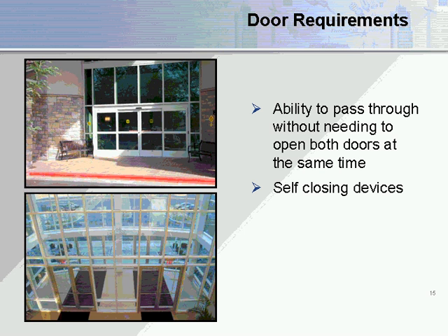Okay, also from a door requirement, we talked about the ability to have self-closing doors. So, what you can use, power-operated doors, the upper right-hand corner, this is a power-operated door. This would be fine. These are used quite extensively in a lot of buildings. A standard self-closing door that we looked at the very beginning of the presentation, again, this would meet the intent of the requirement.